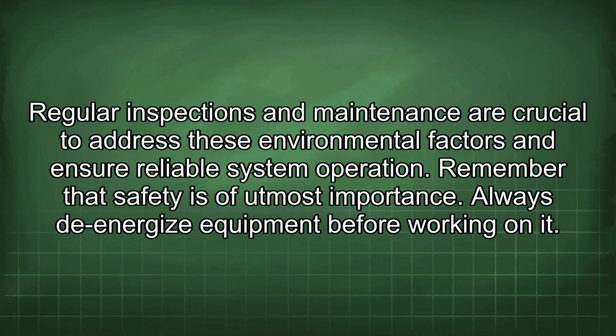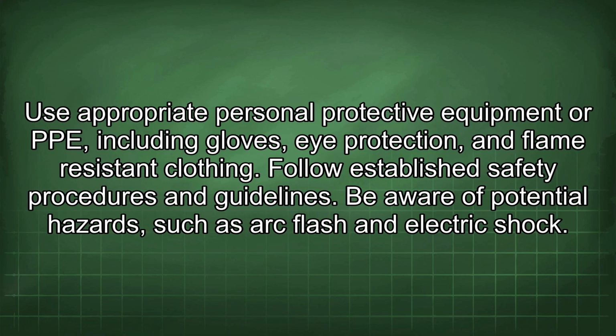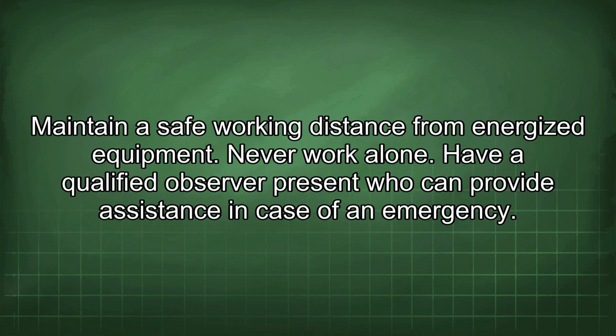Remember that safety is of utmost importance. Always de-energize equipment before working on it. Use appropriate personal protective equipment, or PPE, including gloves, eye protection, and flame-resistant clothing. Follow established safety procedures and guidelines. Be aware of potential hazards such as arc flash and electric shock. Maintain a safe working distance from energized equipment.